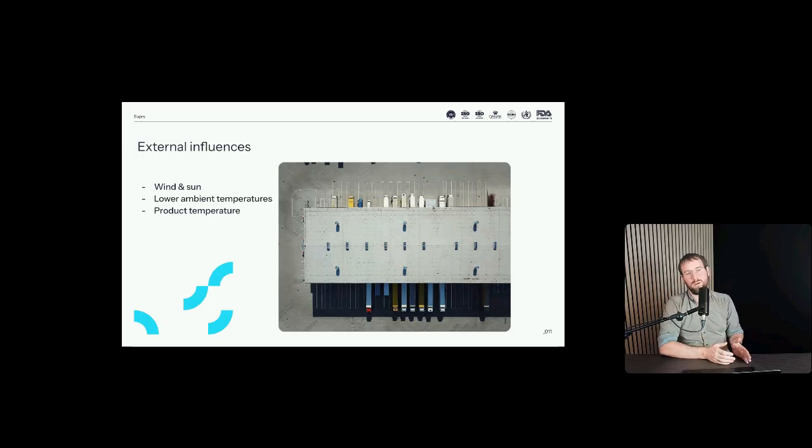And that's really something you can only take care of during the performance qualification, because during normal operational qualification, you often don't have influx and outflux of products. But that really means that when we design our studies, we need to ask ourselves, does normal operation include the influx or the loading or unloading of non-temperature controlled goods? Because then we need to test that as well, or at least have really good risk assessments in place to ensure that we mitigate those risks.